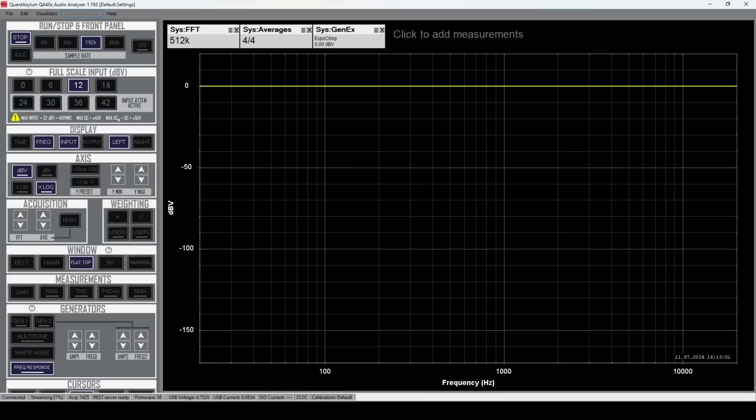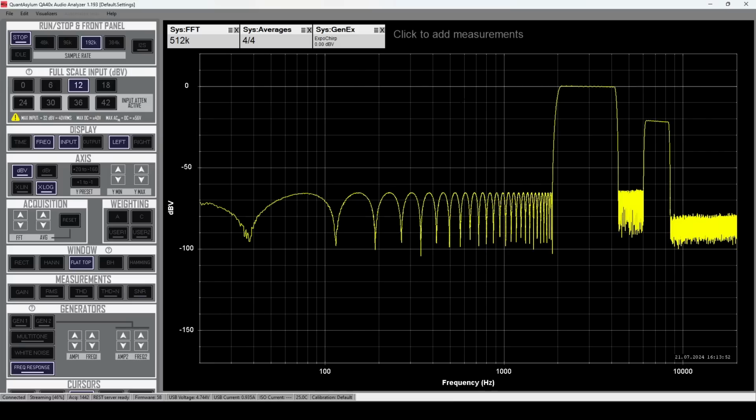With the pedal bypassed, as it should be, it's just a straight input to output connection, we simply have a flat frequency response. But now, with our filter implemented, and this is running the CMSIS DSP FIR function, I'll click toggle, and this is what we get on this plot. Now keep in mind, this is a logarithmic plot.